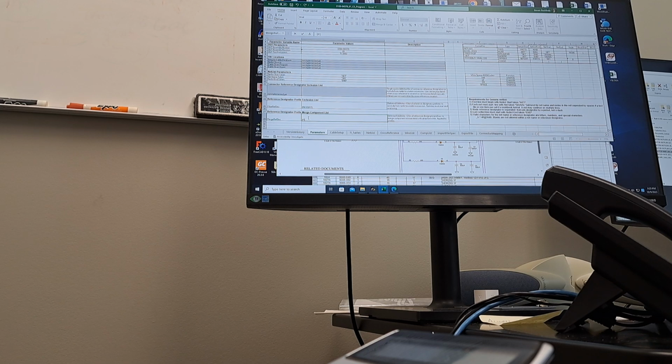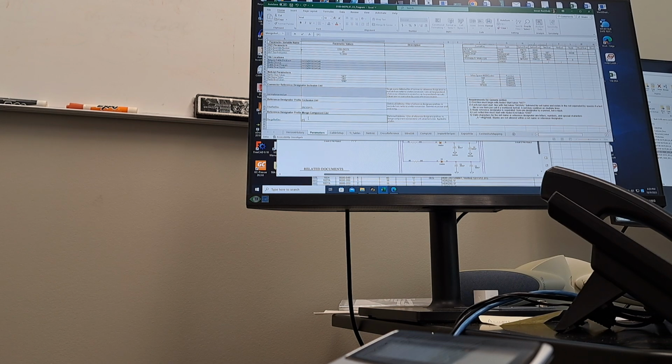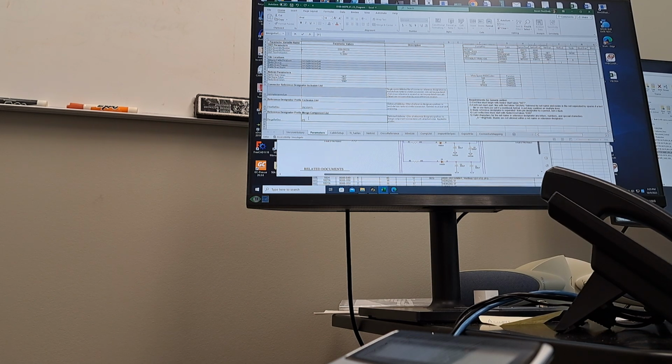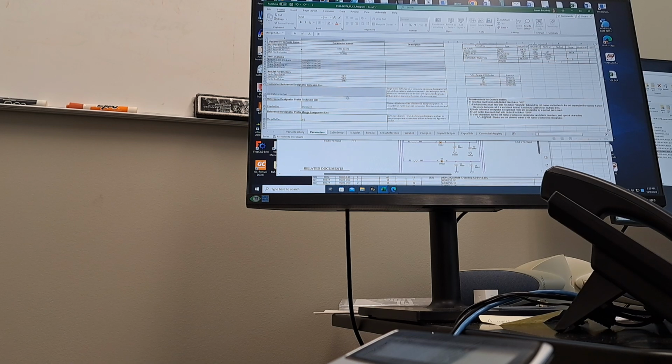I want you to connect. So if I see an F in my net list, I'm going to take F1 pin 1 and F1 pin 2 and put them together to make it a short. That way it just puts it all the way through. So you would just make this parameter called merge ref des.